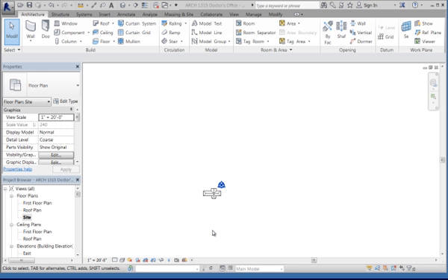Once you get your site made up, and before you put any notes or anything on that, because remember text and dimensions get all screwed up when you change the scale. So before you do any of that, try to place your site plan on the sheet and see if it fits at that scale in case you have to change it. I'll show you that in a minute too. But the next page just goes through a list of everything that is generally on a site plan. So I just wanted you to reference that when you're doing it.